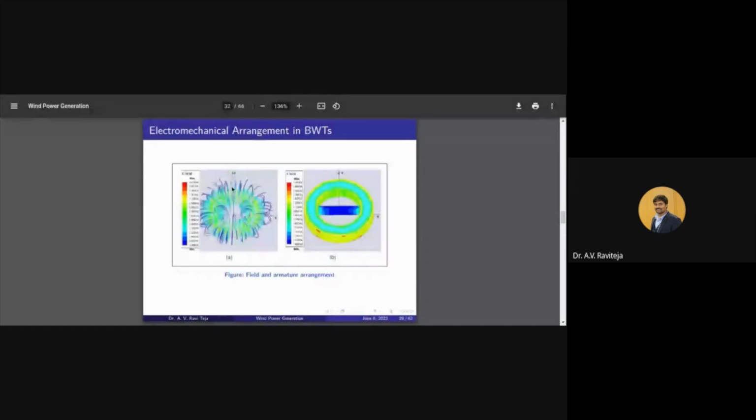Okay. So my objective is, at the center, I want maximum field distribution. If the coil vibrates a little also, I need to get maximum field change. So the field profile is given with this color. Red means more field, blue means less field, and I want a red to blue variation for a small vibration. For small vibration itself, if there is more dφ/dt, then the coils placed on the mast will have higher voltage induced.